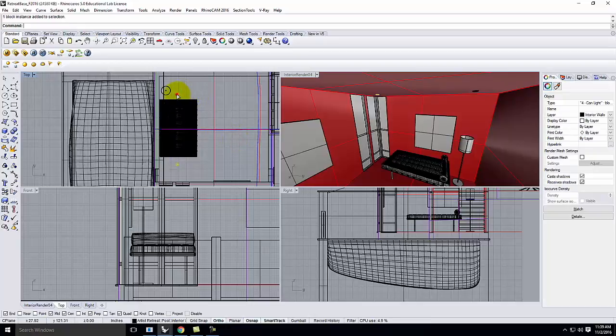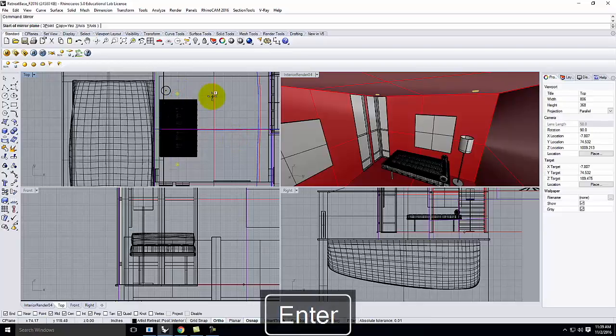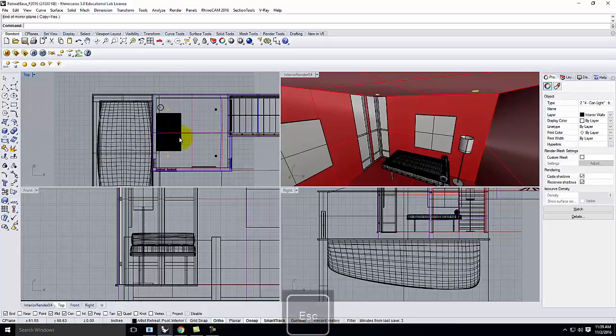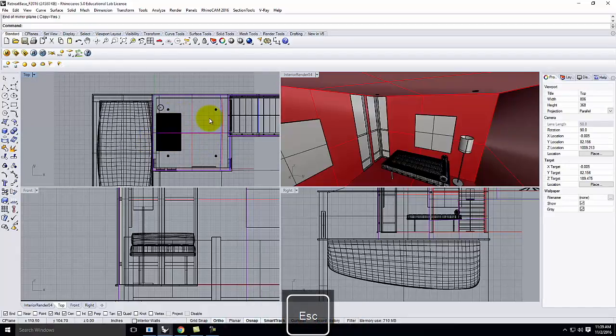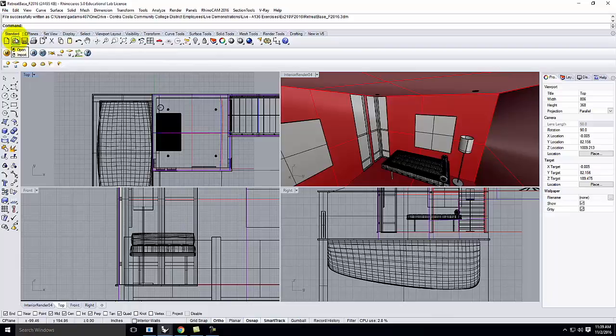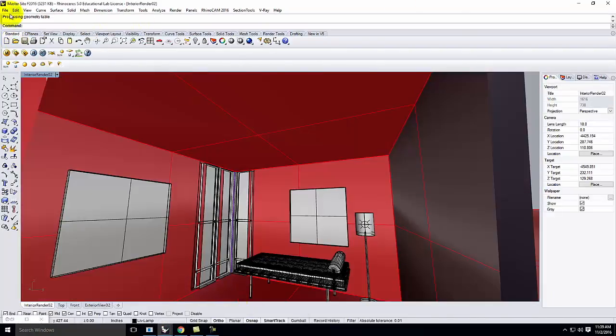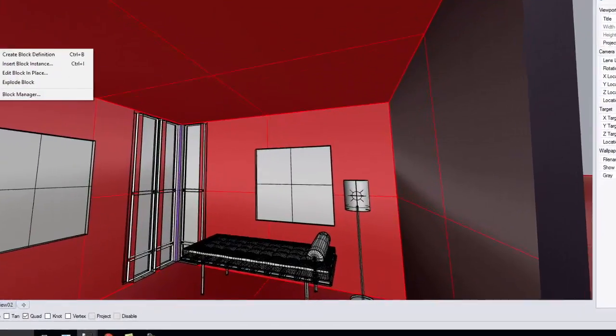Let's mirror it a couple times. We'll mirror there. I'll select both of these. We'll mirror that way, and now we have 4 lights in the room, right? We may find that I need more lights, but I'll start with just those 4. Okay, so the geometry's here. We'll go ahead and save the geometry. We'll go back to my master site, and we'll update my block.